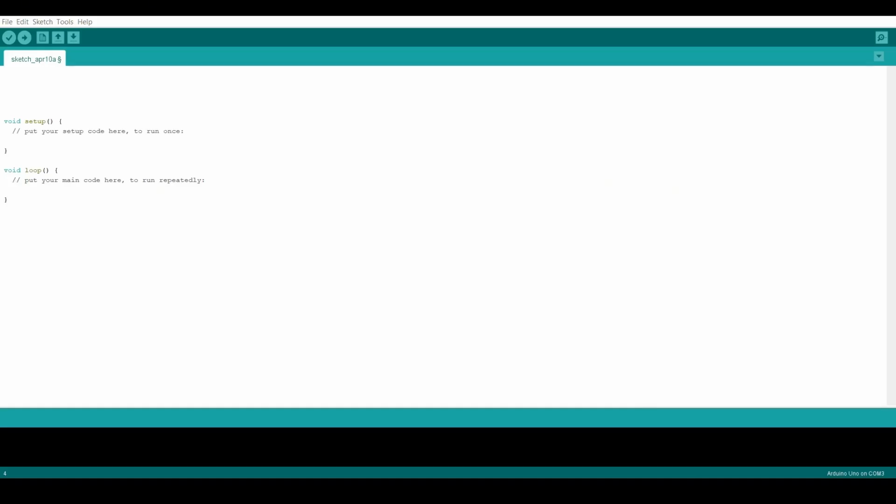8 is going to be for the push button. We're going to use a constant int, and we're going to call it pushButton. pushButton equals 8. Voila. Then a constant int LED, so that's going to be the output. We put it on pin 9.